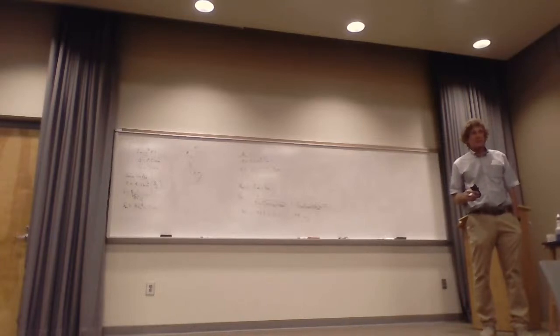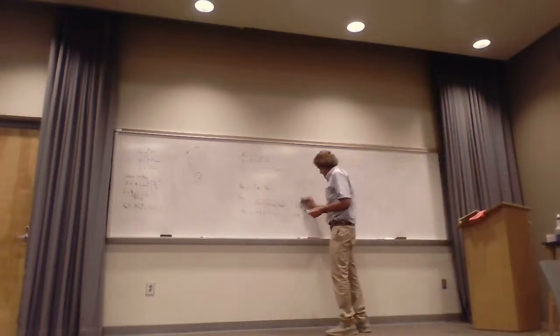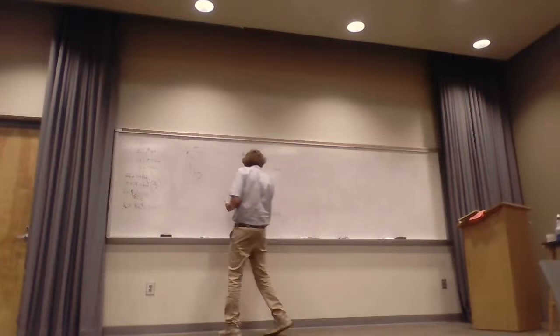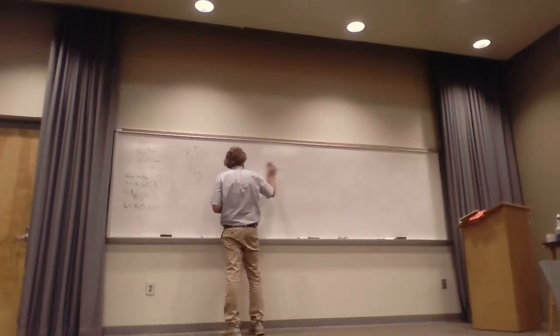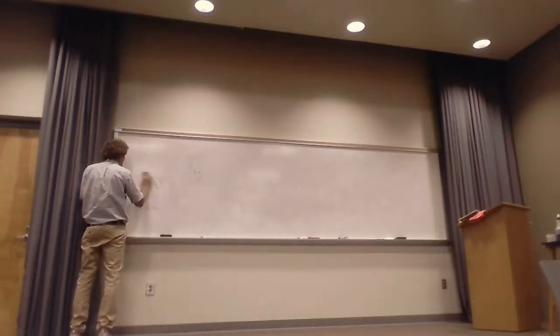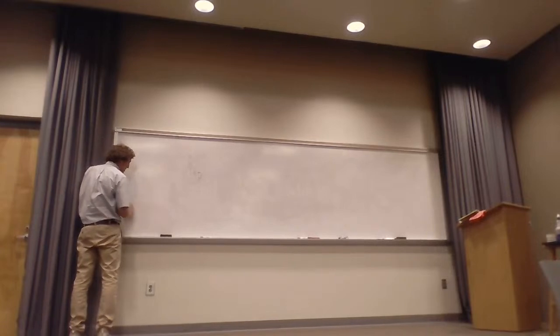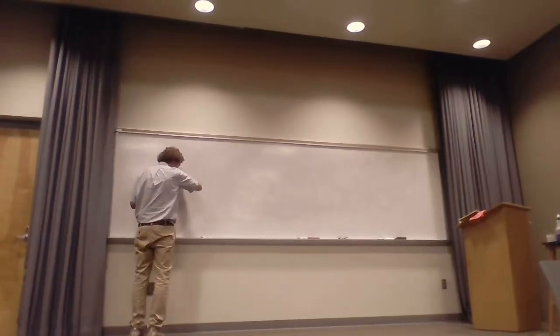In 6.27 part B, you might just be able to answer this without writing it aloud, but you asked for the instantaneous magnetic field. And the equation that you use has beta over the intrinsic impedance instead of 1 over the intrinsic impedance. So I was wondering why. Maybe it's wrong. Let's take a look at this.